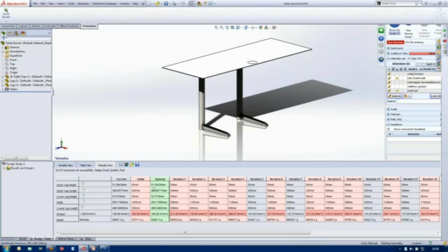Now, this is one reason to use ranges with steps, is you know you're going to get an answer out that represents a manufacturable item. And so you'll get a round number, essentially, as opposed to this where you get very awkward numbers, but it does give you the lowest mass for a stress which is within my 200 requirement.